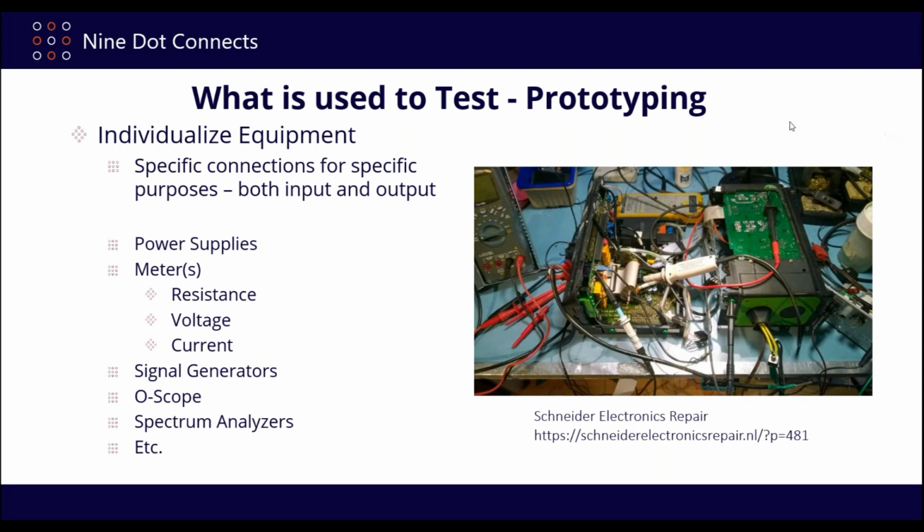Now, on the back over here, what I wish they had shown is what they had in the back here, because there's probably a stack of boxes with all these things that they were doing here. But at least they show you what this looks like. Now, why is this important? Because if they get to this point and they're putting a lot of stuff on this to get some type of signal, and they realize that they can't get a signal, to take this, unstrip it down, get it over to a soldering station to do what they need to do, and then put this back together, you're basically talking about a day lost. So if you have the test points on there and they have to get to that point over there, you've got to save them literally hours, if not an entire day of effort to somehow find that pin and to get a probe onto it.